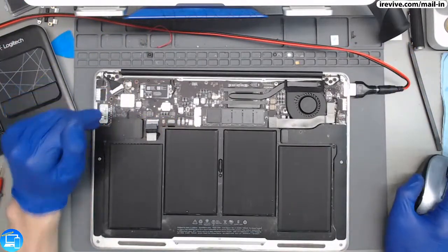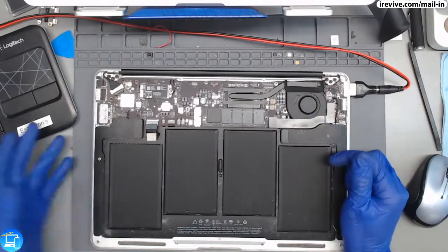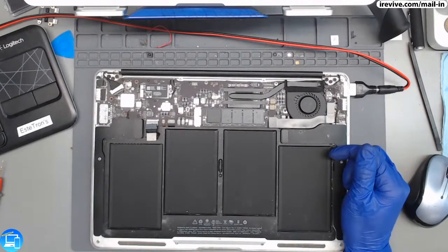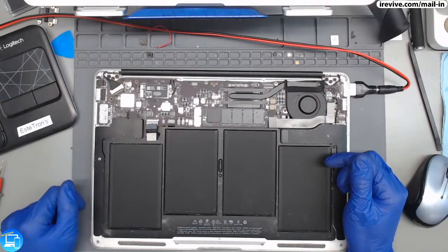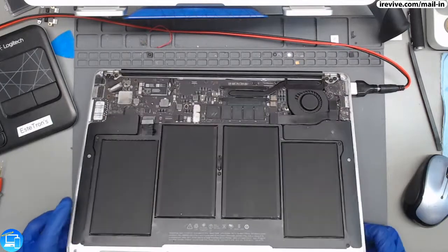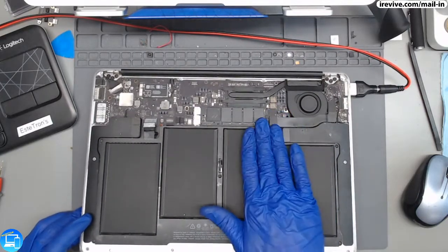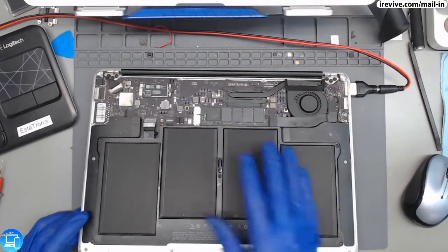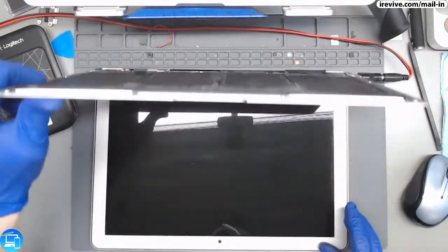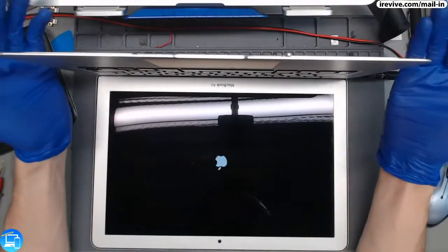So this MacBook is in here because it was just not turning on. A second ago, I actually just saw a fan spin. So let's see what happens when we hook it up to our power supply. So we are drawing about 0.6 amps right now, and we are getting a fan spin. And this is a 3474, I believe, which means the computer is going to boot loop a couple of times before it actually turns on. So screen just went dark, and Apple logo.